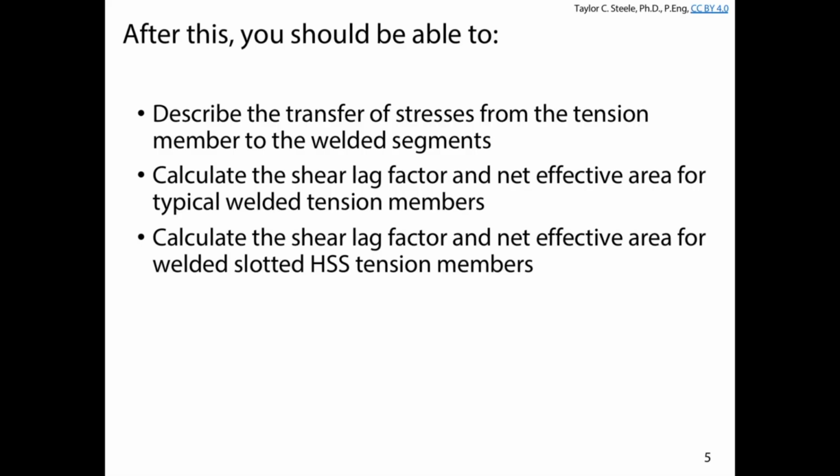And we're going to see we're not usually dealing too often with a shear lag factor. We're going to deal with a shear lag factor for HSS connections. We're going to be directly calculating the net effective area for most other situations. But from the effective net area, we can back calculate a shear lag factor just for comparison purposes with bolted connections. And similarly, we're going to look at calculating the shear lag factor for net effective area for welded slotted HSS connections, which are a special case. Most situations we can do the same kinds of calculations, get net effective area, until we start dealing with HSS, it's a little bit different.